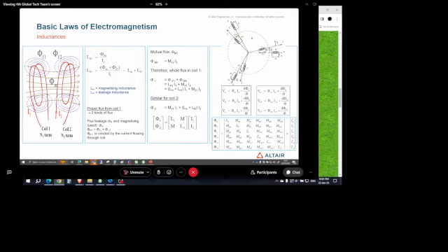So that's why we have this reluctance variation or inductance variation due to the rotor position. And that's why for each working point, we need a given control angle in order to maximize the torque, because this mutual inductance is varying according to the rotor position.